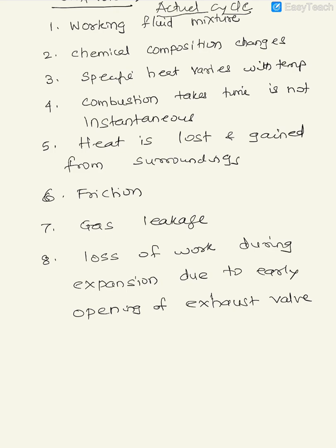As in the fuel air cycle analysis, we consider that the working fluid is a mixture, the chemical composition changes, specific heat changes with respect to temperature, combustion takes time, heat is lost and gained from surroundings, there is friction, there is some leakage of the gas also, and there are blowdown losses. So you see that actual cycle analysis is a very realistic analysis.